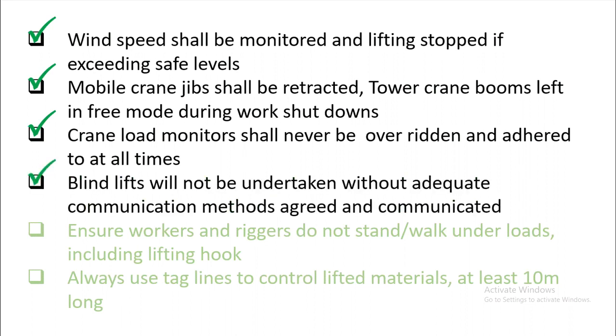Blind lifts will not be undertaken without adequate communication methods agreed and communicated. So this is very important. Where the operator cannot see the load at all times, make sure that there is adequate communication between the operators and the riggers when they are doing the lifting operations, and make sure all of this is communicated, including the affected work area, so as to avoid any incident.